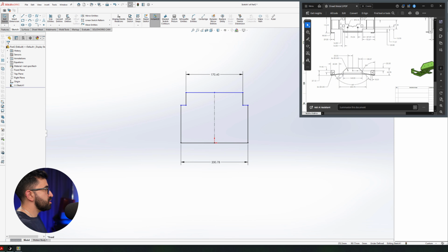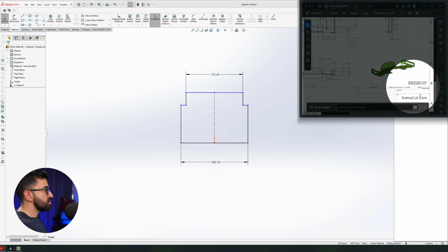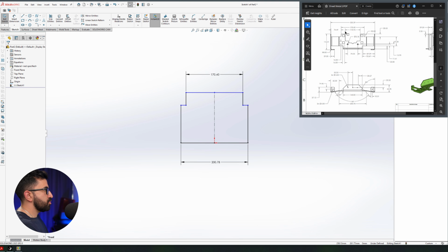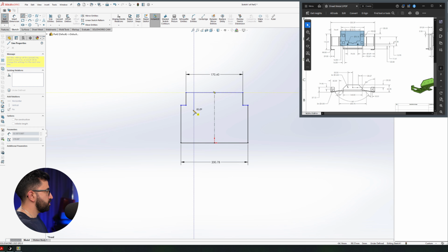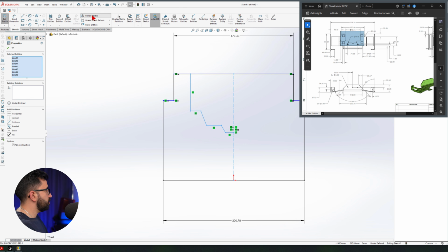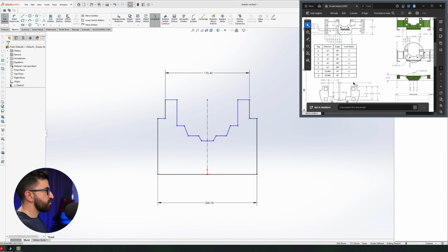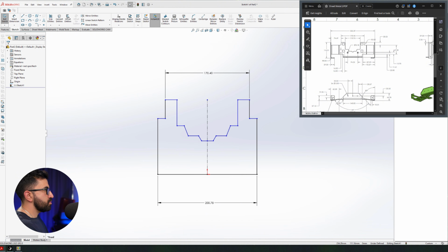By the way, the tolerance and the sheet metal thickness and the sheet metal radius are defined here. Tolerance plus minus 200 microns, and thickness 3, bend radius 5. Now I'm going to do this bit, this area over here. Okay, now the dimensions for it are on the first page here on this detail view,